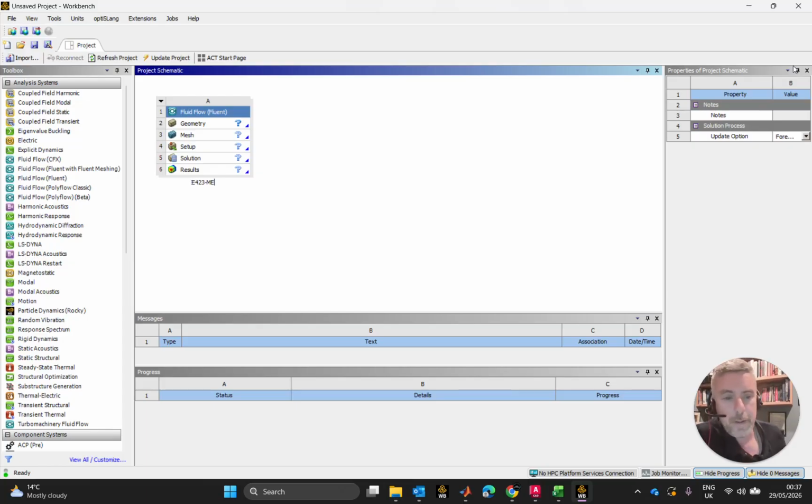Now, if you're doing a parametric study where the parameters are principally solver parameters or variables, use away at them, CAD packages like SpaceClaim and Discovery. However, if the parameters that you are using are to drive geometry, to change the likes of chord lengths and maybe angles of attack, if you don't want to change the angle of the air coming in, if it's the actual geometry you want to change, you cannot use Discovery or SpaceClaim. You have to go to Design Modeler. Design Modeler might be a wee bit clunky. It might not be the smoothest of workflows with respect to developing a CAD model.